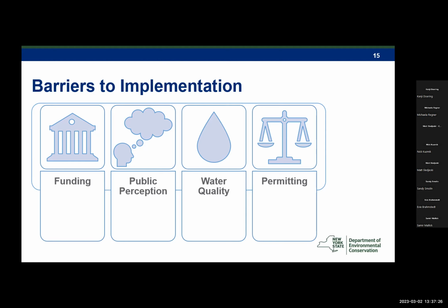And New York State regulates discharges to surface waters through the State Pollutant Discharge Elimination System, or SPDES. And the DEC reviews treatment system designs against Ten State Standards and TR-16, both of which guidance documents include provisions for new or alternative technologies. And the Ten State Standards include language that states the policy of the reviewing authorities to encourage rather than obstruct the development of any methods or equipment for the treatment of wastewater.